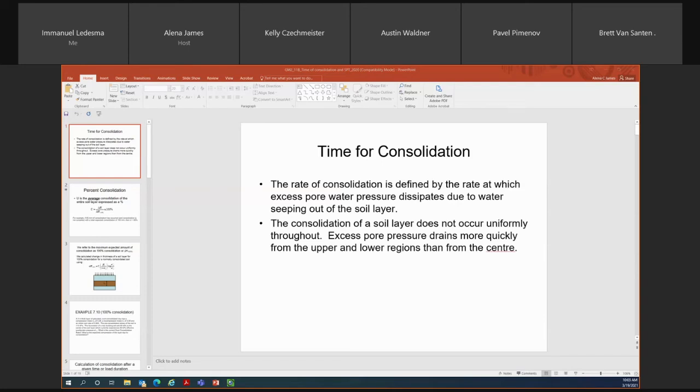Okay, I'm going to answer some questions. So hopefully those who put the questions in here are back. What is the Q in Q times IC? Q is stress or pressure in kPa. So that's what's represented by Q times IC. No, you would only calculate settlement for the corner and the center if I asked you to, but what I strongly recommend is that you calculate the settlement at the center. That's because that will always be the largest amount of settlement that the structure would experience. So always calculate the settlement at the center.